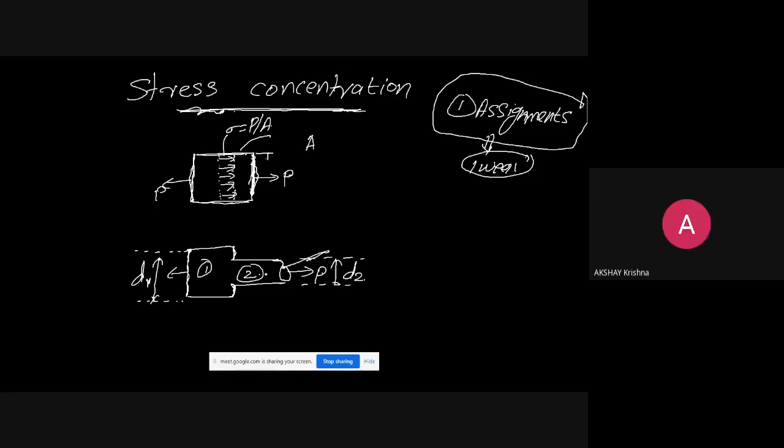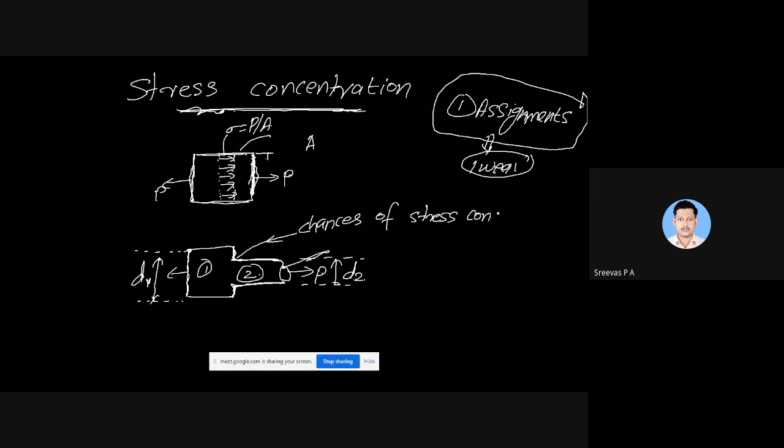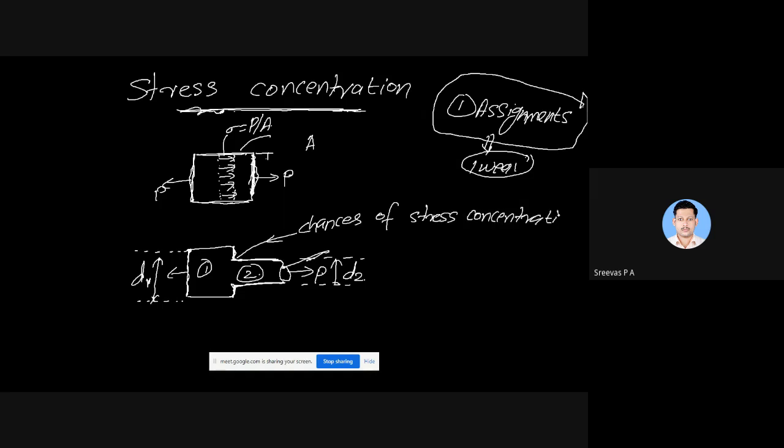So section 2. Okay. In section 2, the stress will be higher because the diameter is less. But if you consider this side, here some sharp edges are there. So due to these sharp edges, there will be chances of stress concentration. Okay. Stress will be somewhat higher.